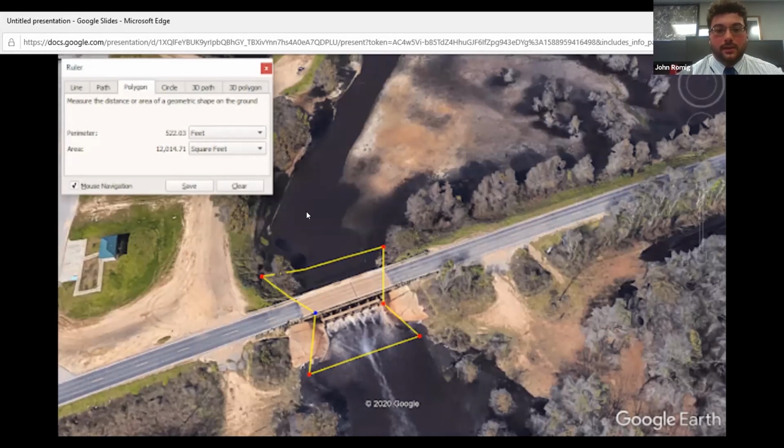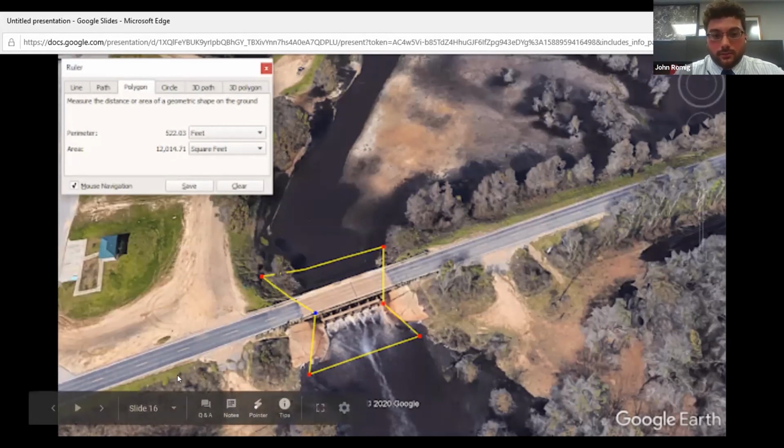And then we also needed to figure out what kind of pump we were going to use, and how much water we were going to have to pump out. We did some calculations, and we used Google Earth, and it shows about 12,000 to 13,000 cubic yards of water would be located in that area. That's just a little tool we used, and that's how we decided which pump to go with.